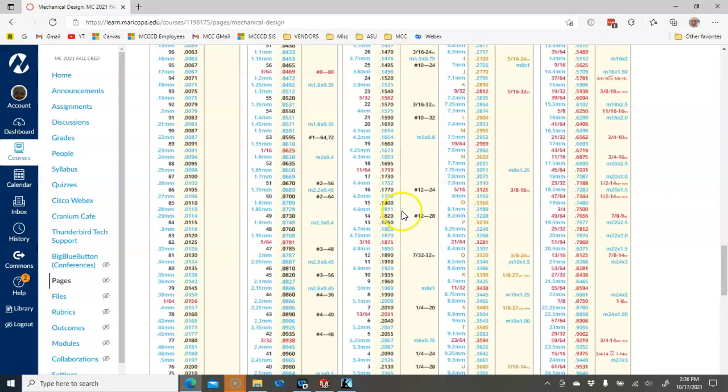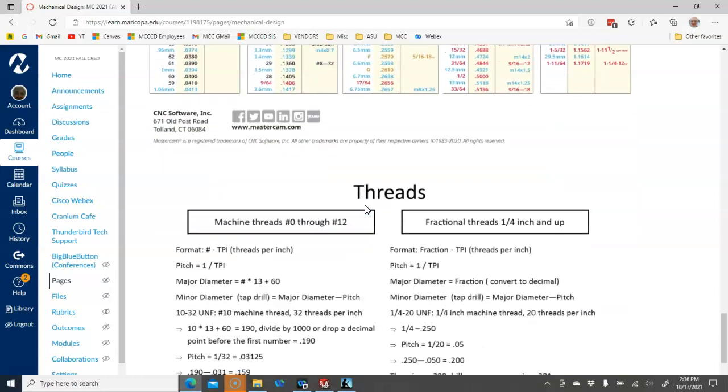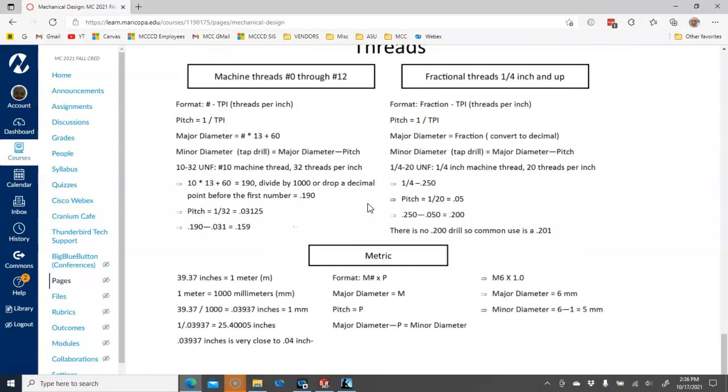with the machine. You're going to need to have some extra oomph on it, because it's a big thread, and because of the taper, they are sealing as much on the compression, and can even go to dry seal, where the threads lock and become tighter as you turn the fitting in. All right, so rather than carry one of the charts around, or carry around the Machinery's Handbook or the Marks Engineering Handbook, here are 3 formulas that you can jot down, memorize, work with, to have that same level of information for our threading.